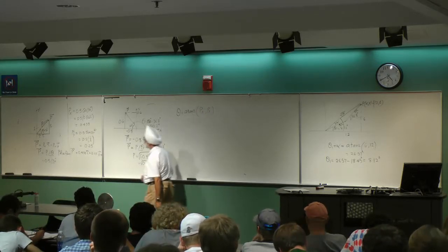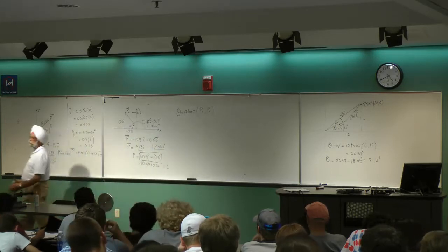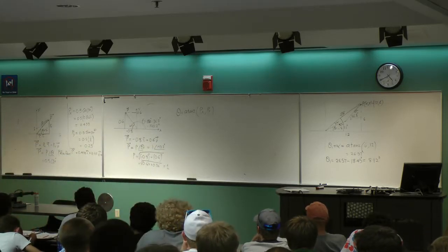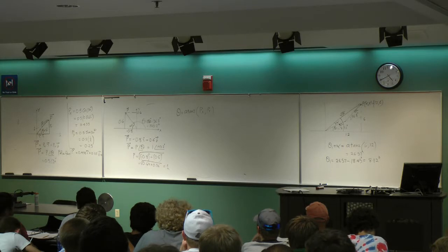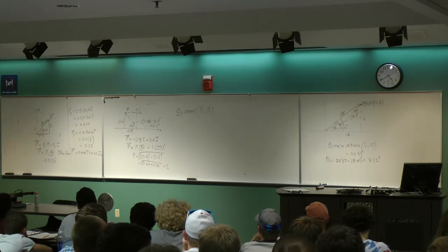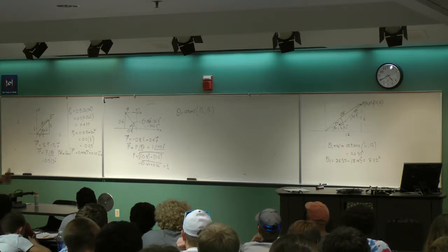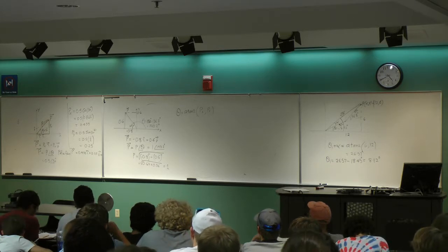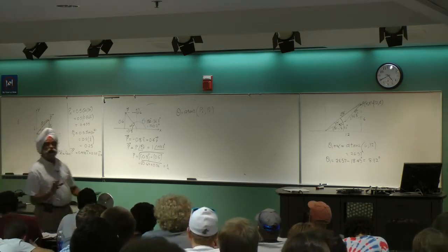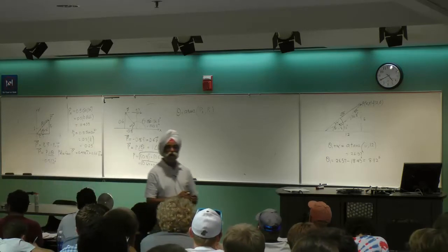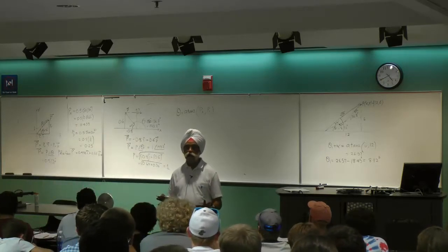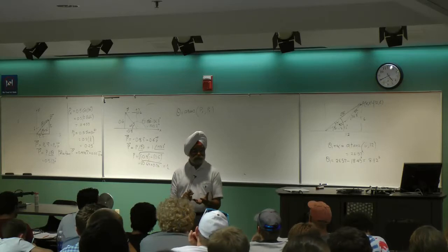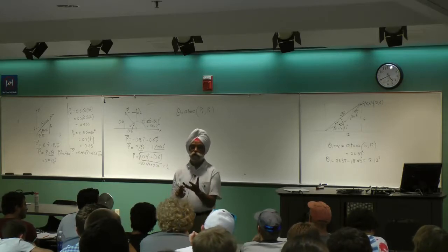By the way, this angle generally is defined as arctangent of py divided by px, right? Sine over cosine. But this will give you a wrong answer in some quadrants. I will forget about atan from now on. I'll always use atan2 or the reference angle.